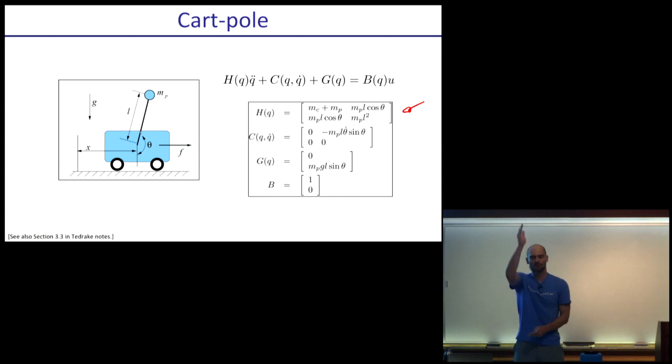Now, if we start perfectly upright, nothing's going to happen in a simulator. But if we start from a state away from the equilibrium state, we'll be able to check if our feedback controller indeed brings us back to the equilibrium state or might fail. And you say, why would it fail? It's supposed to control us to 0, but that's only true for the linear system. For the nonlinear system, there's no such direct guarantee that it's going to go back to the equilibrium state.